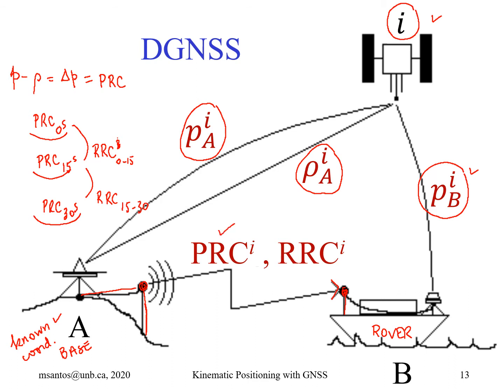They would have the pseudo-range correction and the rate of change, which means that the receiver, or the computer associated with the rover, can then apply the pseudo-range correction computed directly from the rate of change to the pseudo-range that it observes.